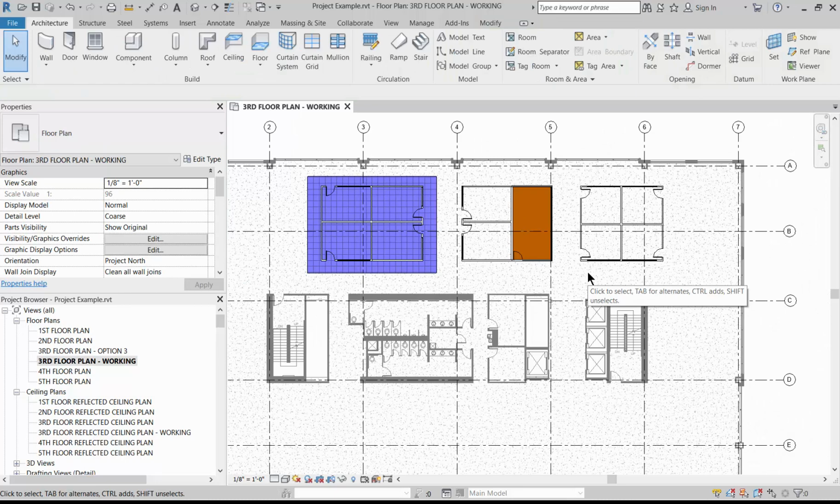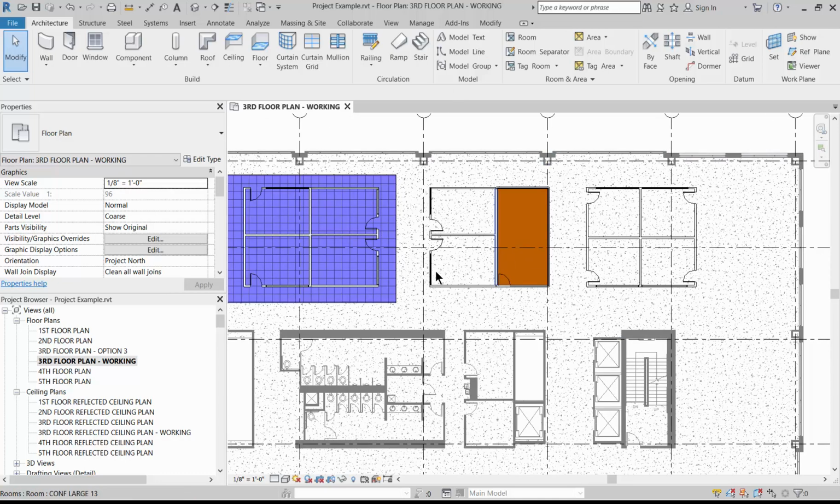You might have several more flooring types. You might be using resilient floors. You might be using stone or a tile floor, depending on your spaces. So make sure you define all of them and use color wherever possible because of your scale, and pattern only should be shown if it's large enough pattern to work with your scaling. Now later on, as you're showing enlargements, you might be wanting to show the floor pattern.